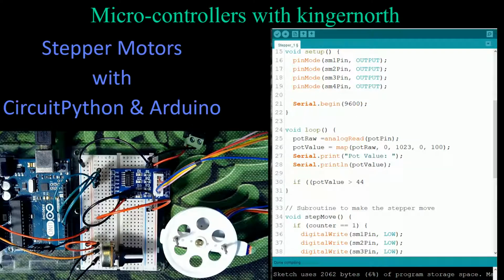What we're doing is we're going to create what's referred to as a deadband in the middle of our pot. So basically from 45 to 55, I don't want this thing to move when I'm adjusting the pot. I could say 50. The problem is it's hard to adjust from 49 to 50 and to 51. So I'm giving it a range, so I just have to be approximately in the middle. I'm going to give myself some leeway. So I'm going to go bracket, but when it's greater than 44, it also has to be less than 56.